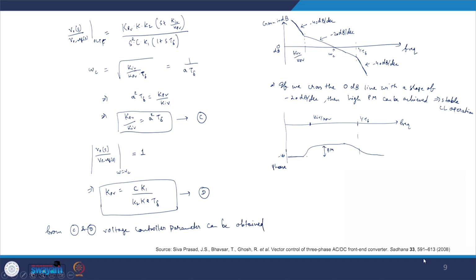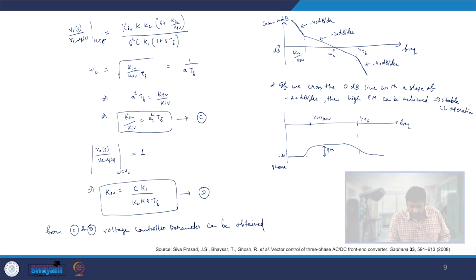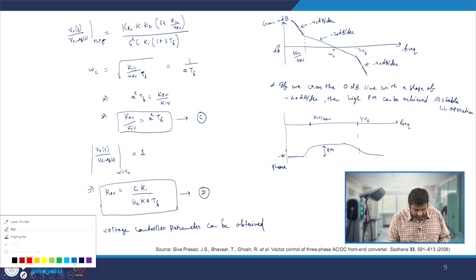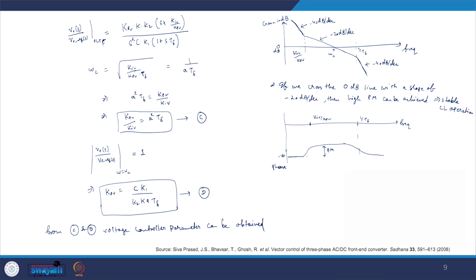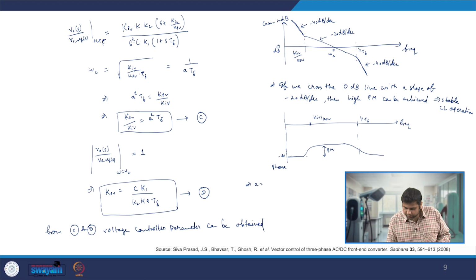If we look very carefully in this particular system, we have missed one quantity which is A. So this A value is the one which will actually determine your phase margin. Whatever the value of phase margin you take, accordingly your things will be determined. So if we take A equal to 2, from this transfer function you can calculate your phase value.